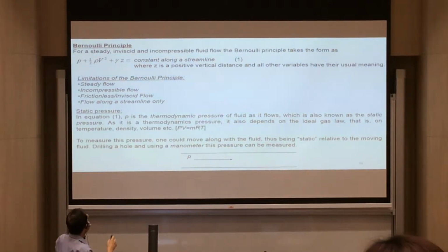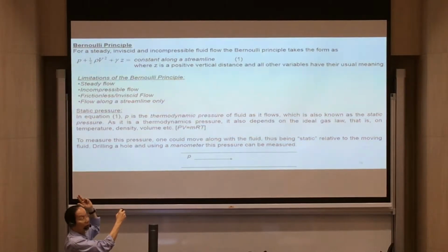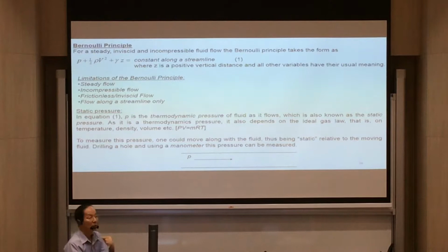Now, bear in mind, these are the conditions where this Bernoulli equation will apply: steady flow, incompressible flow, frictionless, inviscid, non-viscous, and flow along a streamline.